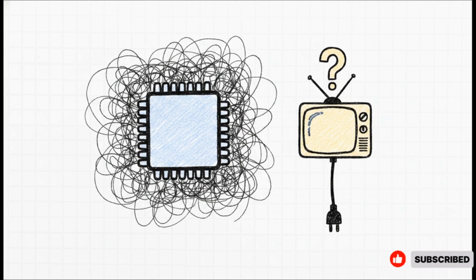Recognizing a failure to terminate these data echoes is super important. When the DDR terminator chip shorts out, you get unwanted data skipping and massive signal interference. The TV's core processor just gets entirely confused by the noise and gets stuck in a desperate reset loop. And this results in probably the most mysterious symptom of all: random intermittent TV shutdowns. Your television will just turn off by itself at completely unpredictable times. You might literally be wondering if it's possessed, when really, it's just drowning in data echoes.